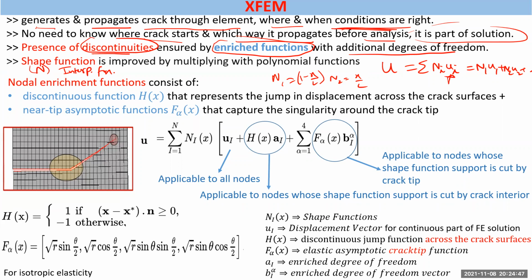Shape function is how it varies from one node to another node. That's the polynomial for a beam. It varies cubically and so on. So that's core to finite element analysis, these shape functions. So that's why we have done some theory. We didn't completely focus on Abaqus. Otherwise, you will not know why we are doing these things. So shape functions are called interpolation functions. That's how the displacement is interpolated from the nodes to any location, intermediate location also we want.